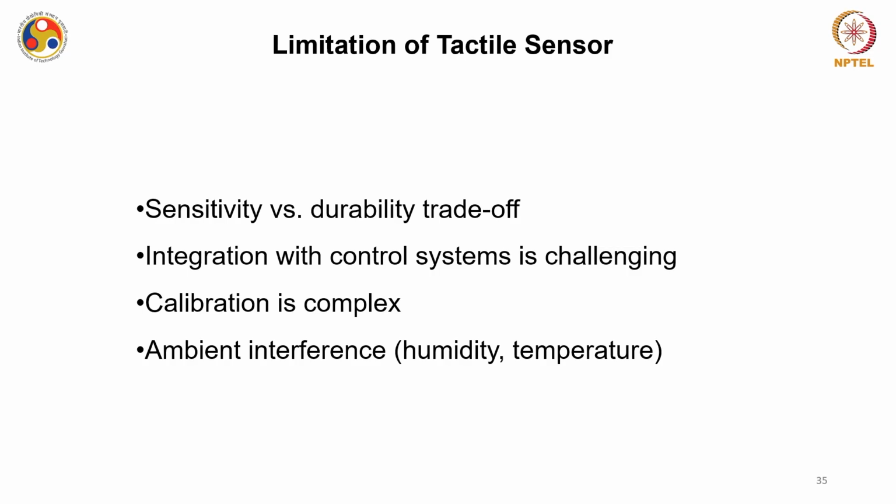Also, what we are talking about is mostly the normal force, but there are other kinds of forces that can be exerted, and that is why calibration is even more complex. When you talk about shear forces and others, it becomes even more complex. Then the ambient interference from humidity and temperature conditions is one of the major challenges for these tactile sensors.